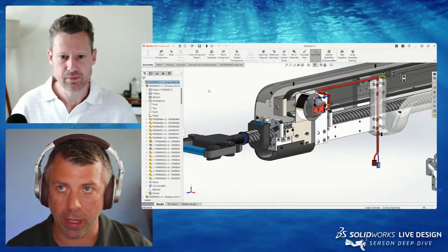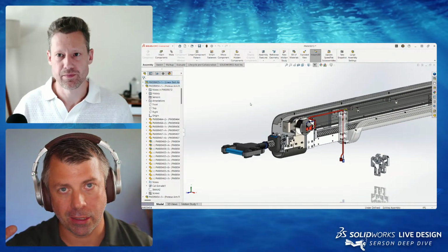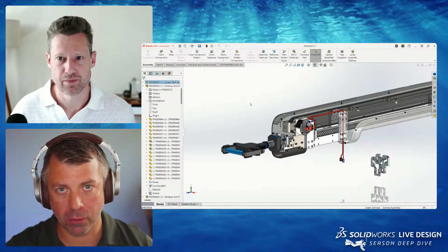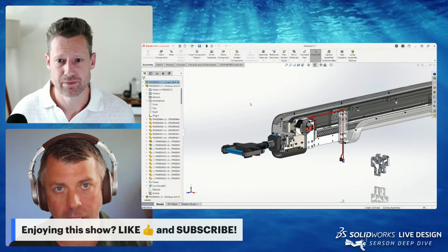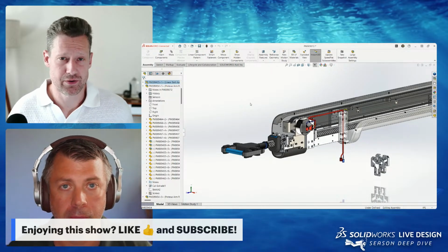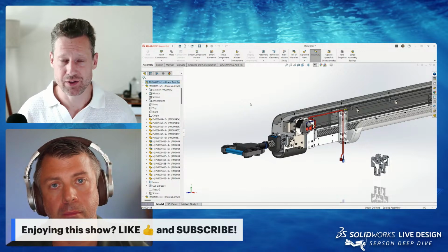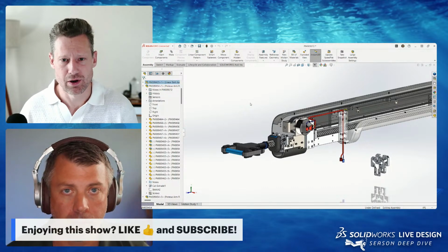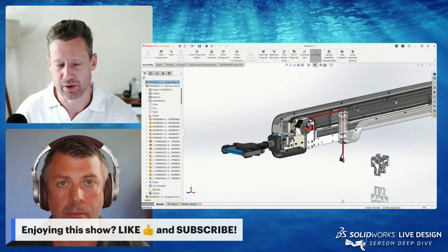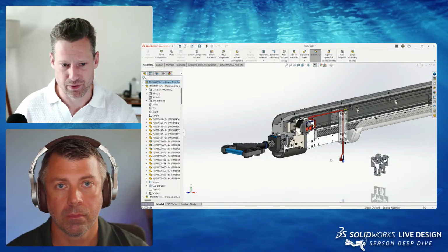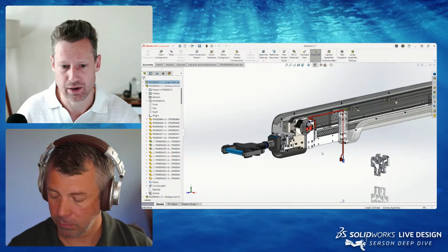So then that new optimize mode that you pointed out really kind of takes away having to figure out which is best for you. It sounds like you just kind of turn it on and let SolidWorks do its thing. Exactly. Yeah. It loads it as lightweight, so it only loads what's actually necessary at the time. Because I mean, you're loading a large assembly. It's not like I'm going to go in and edit every component and I need to see every detail of every component. I'm probably just loading it to do a specific task or to edit a few components.